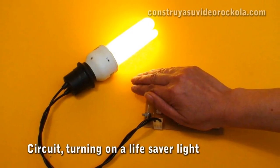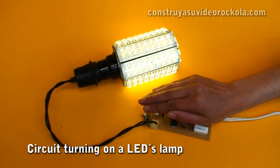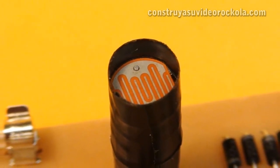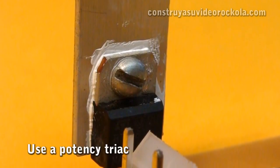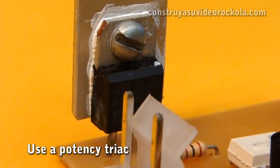This circuit operates with voltage from 115 to 220 volts, no need to make any changes. You can light a bulb up to 100 watts. If you want to power more powerful lighting devices, you should only change the BT136 triac for one that supports more amps, such as the BTA08-600, which supports up to 8 amps.